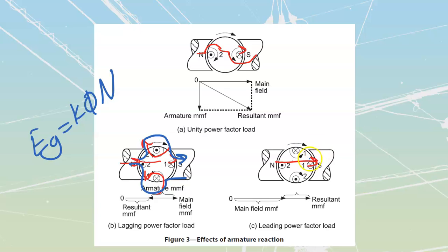If I go to a leading power factor, that leading power factor is now going to give me rotation on this one like that and on this one like that. This is just going to be off of the generated values. Once again, don't stress too much about trying to envision where they come from. We're just explaining why these terminal values of voltage are going to increase. What we're seeing over here is that lines of flux that normally would have been evenly distributed across, like on the top one over there, are now going to get grabbed and all mashed down into the centers.